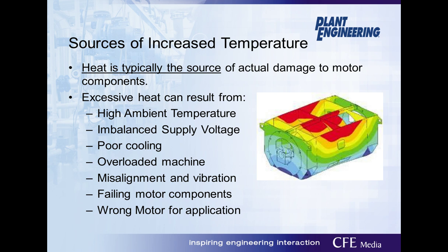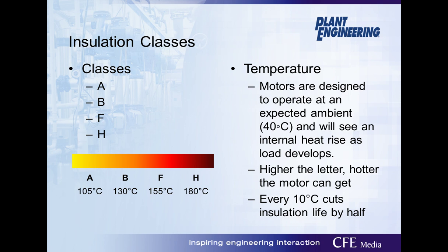Remember what I said earlier: heat kills motors. Heat is typically the source of primary damage to motor components. Excessive heat may occur from items such as elevated ambient temperature, unbalanced voltage at the mains, blocked or limited fan cooling if there is a fan on that machine, machine overload, vibration from shaft misalignment, and even incorrect motor selection for a specific application.